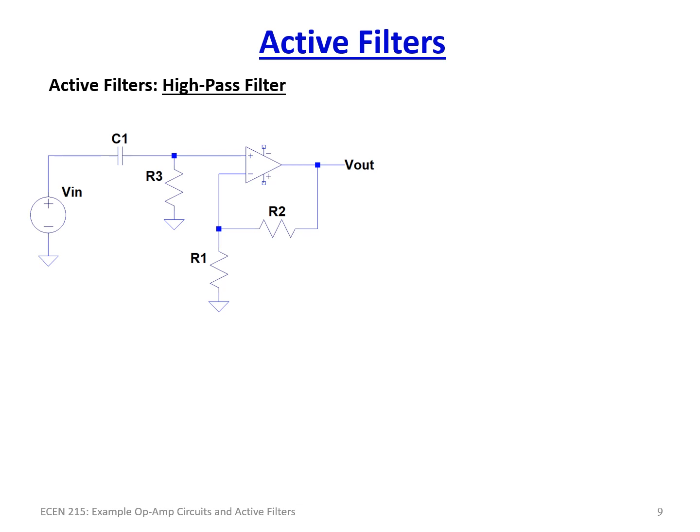Correspondingly, we could flip the circuit around, change the position of the capacitor and resistor, and now the very same filter can be used as a high-pass filter. If we do that, we end up with this as our transfer function: 1 plus R2 over R1 multiplied by F over FC. This part here is the high-pass filter transfer function, and it's being multiplied by our 1 plus R2 over R1 equation for a non-inverting amplifier. So same non-inverting amplifier gain section, but we've just changed the filter on the front end.